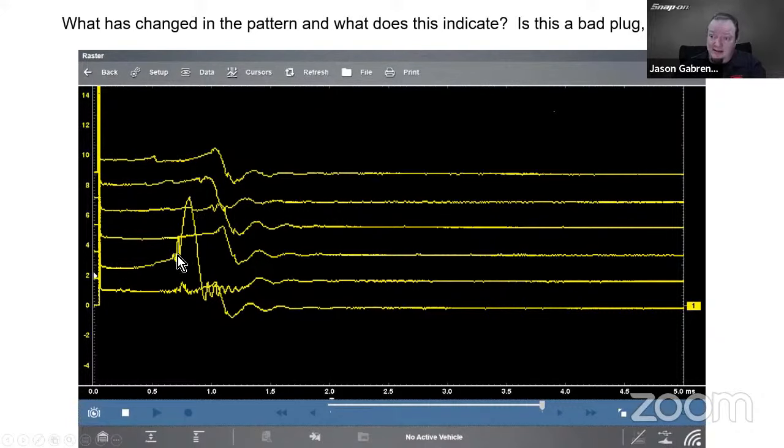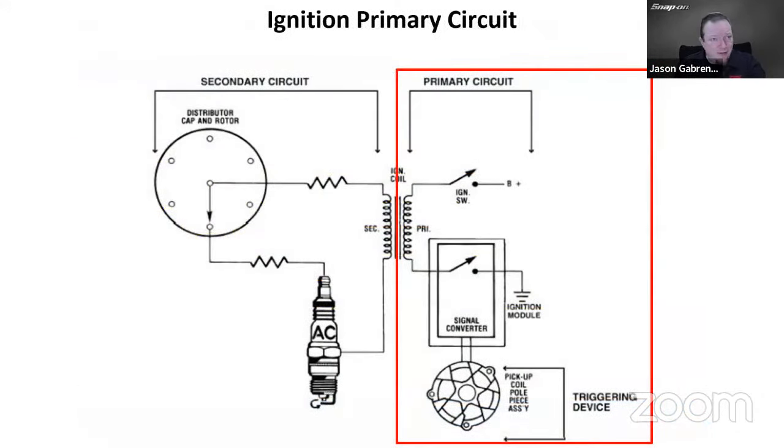So in this case, they ended up tracking it down. It wasn't anything to actually do with the ignition system, but testing the ignition system helped them to suss out that it was a bad fuel injector. Just a clogged fuel injector, wasn't spraying enough fuel under a load, and that was causing it to run lean, and it was giving it a lean miss on that cylinder. So one of many examples of why we would want to test ignition systems. Even into 2024. Crazy, right?